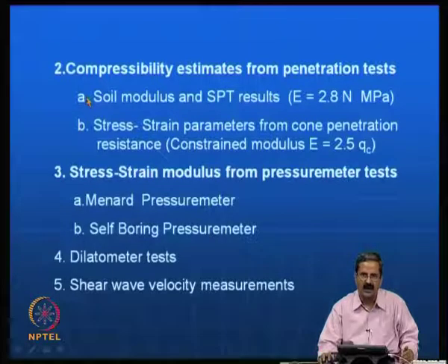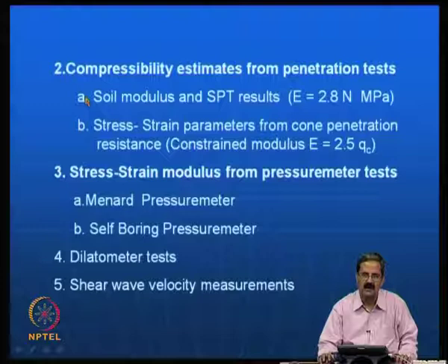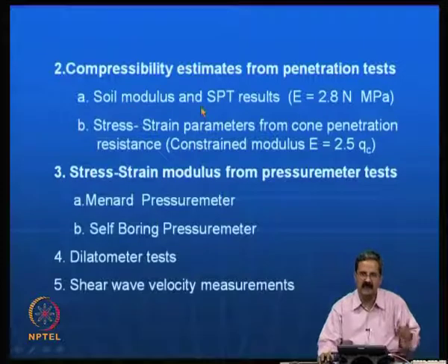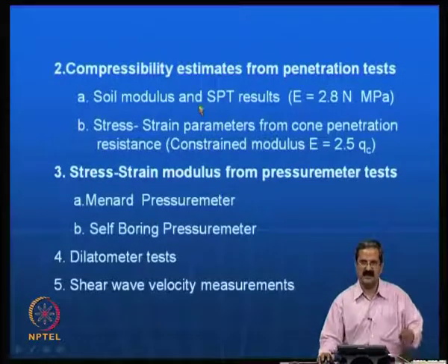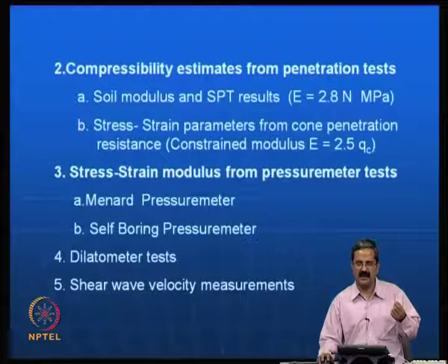As I just mentioned, settlements are very important. So, if you want to measure settlements, you need to have proper instrumentation and also you need to estimate settlements. For example, you have an SPT value N, say 10. If you want to use a modulus in any of the finite element calculations, you need to have these parameters for analysis. Once you do an SPT test or a CPT test, how you use that in the analysis and design is very important.